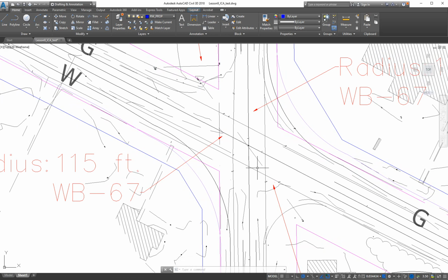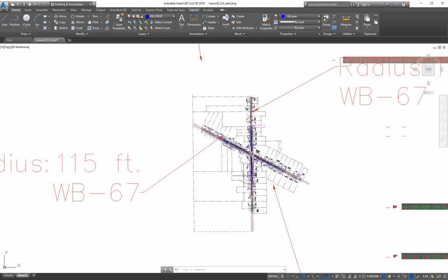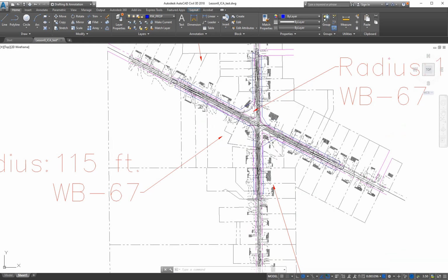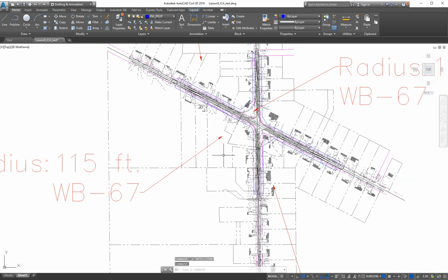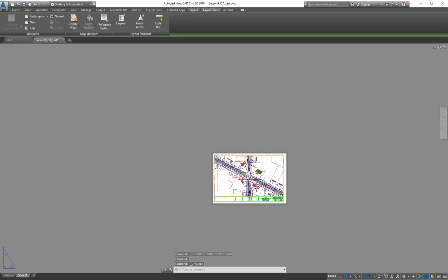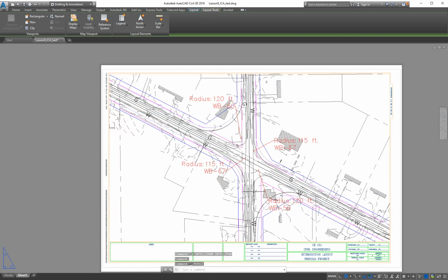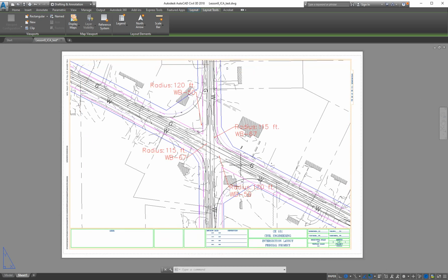I'm like, okay, I'm done. I'm going to zoom back out and see where I'm at. And you zoom out, like, oh, crap. I didn't want to do that. So you got to undo, Control Z, or U a bunch of times, right? Let's get back in there. Now switch it to paper space. Now zoom out. Okay, that's back where I wanted, right? This happens all the time. So don't feel bad if you forget which one you're in.